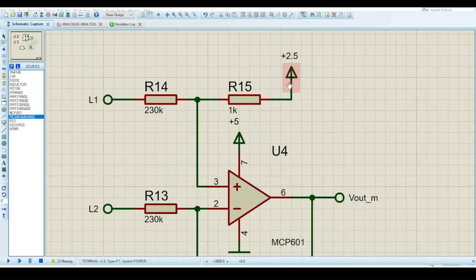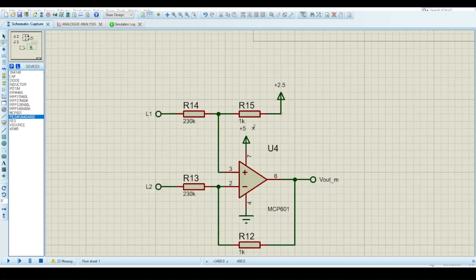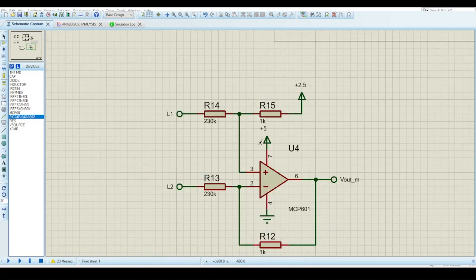It's got a 2.5 volts offset. That's to ensure, because obviously the AC voltage goes through the 0 point and goes negative as well, and the microcontroller cannot handle negative numbers. Well, at least this one is not configured at this point in time to deal with that. So essentially, we're going to offset everything by 2.5 to ensure the minimum value we send is in fact 0, and then the 0 crossing will be 2.5.